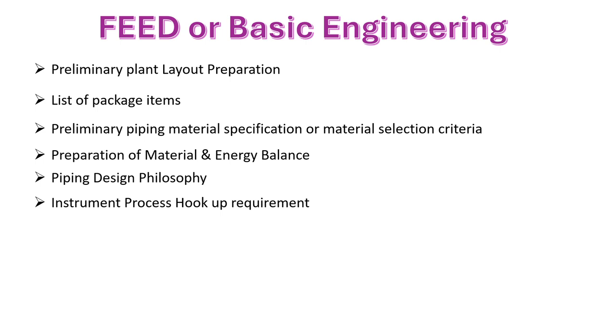Then instrument process hookup requirements: how we are connecting the instruments, air supply, and process connections. That is part of the hookup diagram. We will discuss how the hookup diagram looks for each and every individual item in the next sessions.